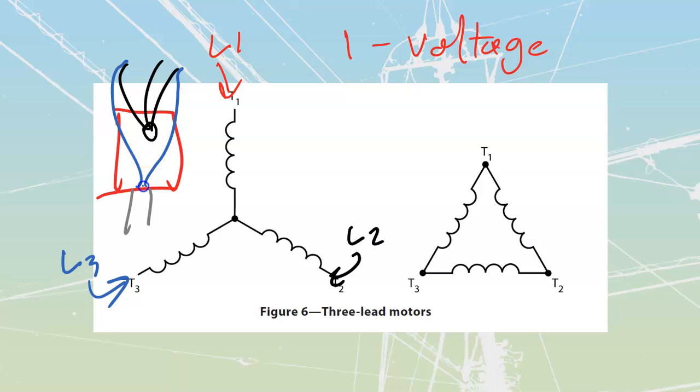If I have the type of terminals that are going to be ring terminals, I'm going to run a bolt through, and then I'm going to rubber tape, followed by vinyl tape. And then I'm going to try and make sure they're not going to sit anywhere where they're going to rub. If I don't have those ring terminals, what I'm going to do is use my morettes or wire caps or solderless wire connectors, whatever you want to call them. But when you place your morettes on, you have to, well, you don't have to, there's nothing in the code that says that you have to, but it is just good form.